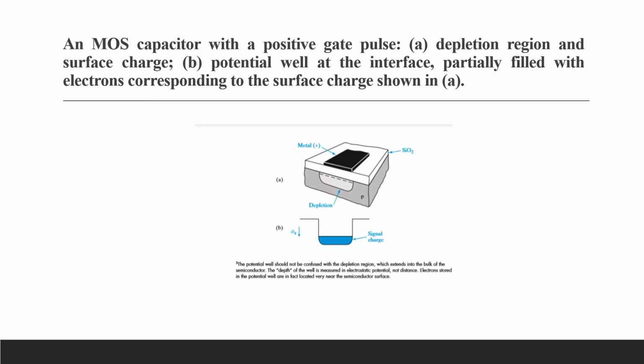This CCD or charge coupled device is one of the most interesting and broadly useful integrated devices. The CCD is a part of a broader class of structures known generally as charge transfer devices. These are dynamic devices that move charge along a predetermined path under the control of clock pulses. These devices find application in memories, various logic functions, signal processing, and imaging.